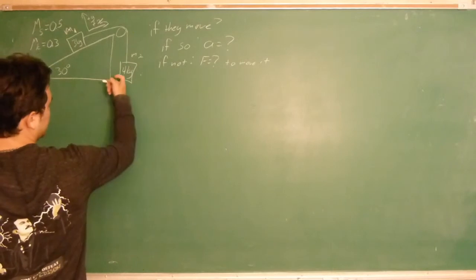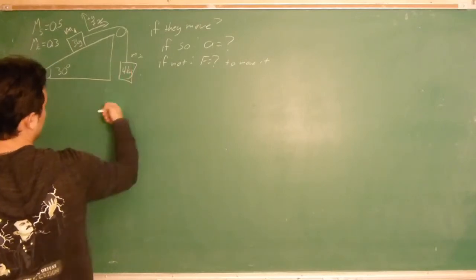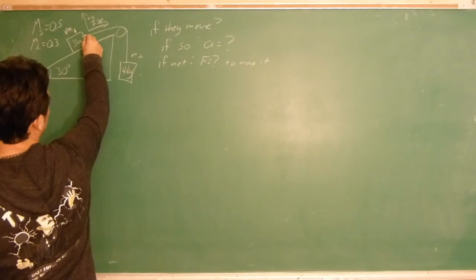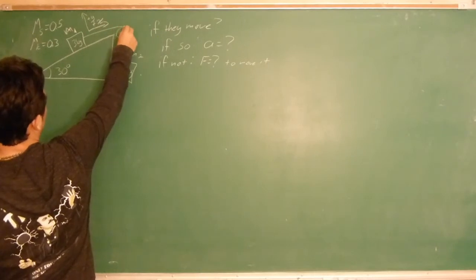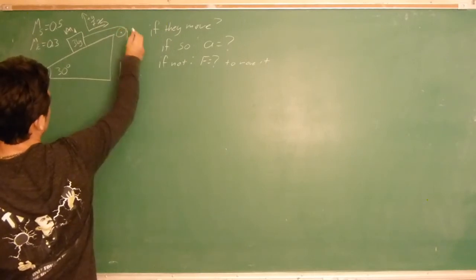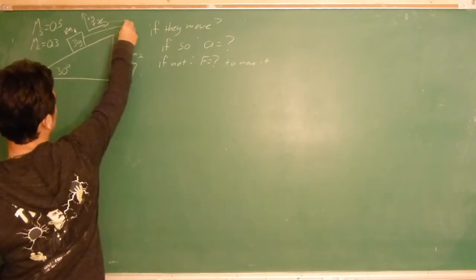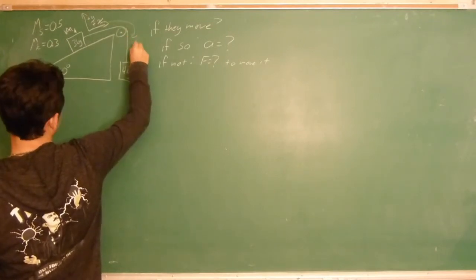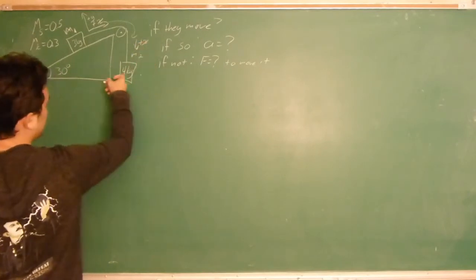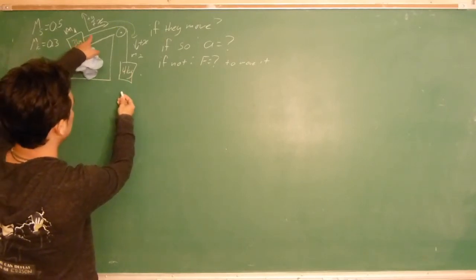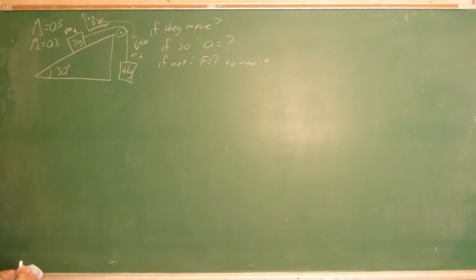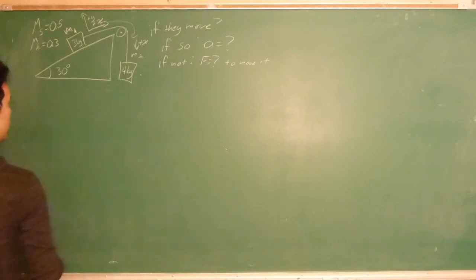Well, the last thing I need to do is see what my coordinate system is like for this guy. He's just going to move up and down. But remember, I've already declared that I've got my positive x direction over here along the plane. And in that direction, that's where our wire goes, and it goes around this frictionless pulley here. Okay, so our x direction actually gets bent downward, and this is going to seem a little strange, but in this case, down is plus x for this guy. Because if he moves a little bit down this way, this guy has to move a little bit that way. They're both moving in the positive x direction. I've got to make certain that the movement of one represents the movement of another in the same dimension. Okay? So, I've got that.